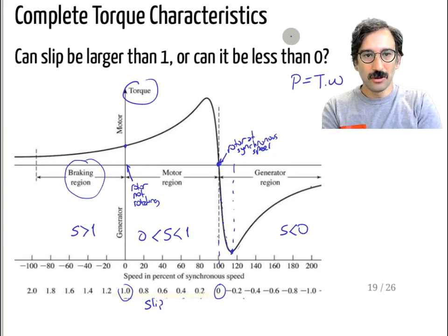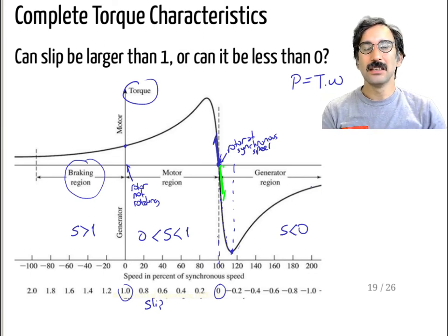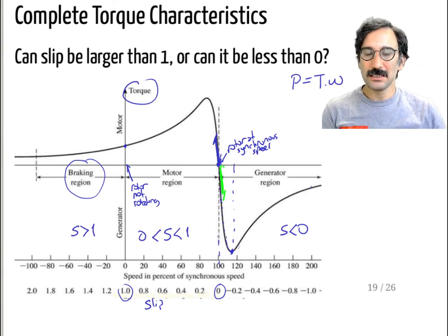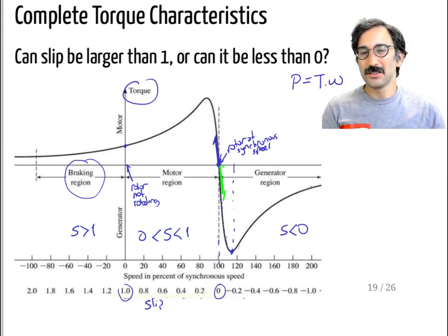For motoring mode, we were operating through that range, and for the generating mode, similarly, we will be operating at small slip values, in this range. Technically, it is the same analogy as with the synchronous machine and the DC machines. Generators and motors are not two separate devices. Generating or motoring is just an operating mode. The same machine can be run as a motor or as a generator.